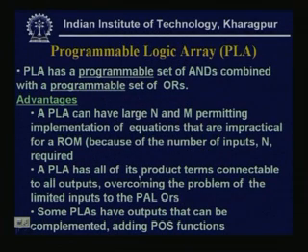Now, a PLA has all of its product terms connectable to all outputs, overcoming the problem of the limited inputs to the PAL ORs. See, a PLA has all of its product terms connectable to all outputs.